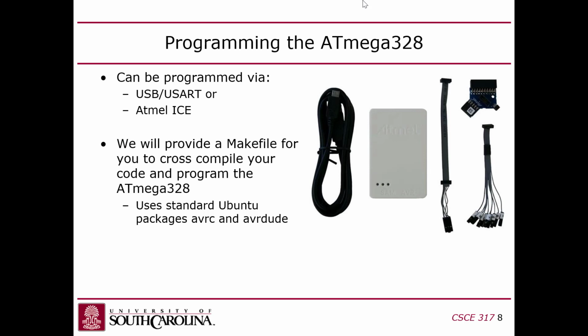And so, as with any embedded system, you write the code on a standard desktop workstation, and then you compile it using a cross compiler, which is a compiler that will take your code and convert it into a binary form that won't run on the Intel machine you're using to write the code, but instead is intended to run on another architecture, another processor.